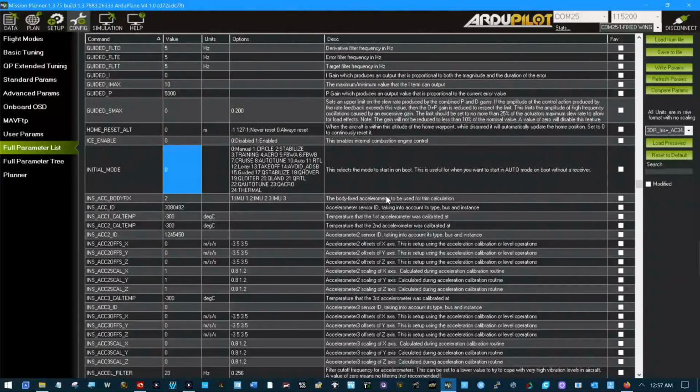The ESC would see that it's getting a high throttle number and know that it needs to go into calibration. Based on the programming manual for the ESC, it will tell you how you need to do the calibration for just straight ESC calibration. You're not wanting to program it for brake or anything. You're wanting to program it for calibration.